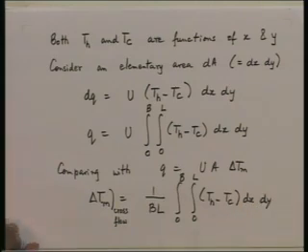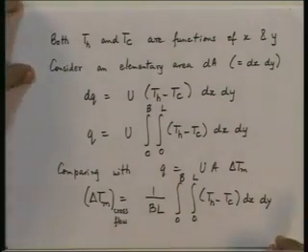That is our expression for delta T m in cross flow. So, you can see it is more complicated than we had earlier. We have now got a double integral which has to be handled. So, the determination of delta T m is going to be much more complicated. It has been done numerically. So, we do not have to worry about it, we will get the results, but it is not as straightforward as it is for parallel flow or for counter flow, which were one dimensional problems.